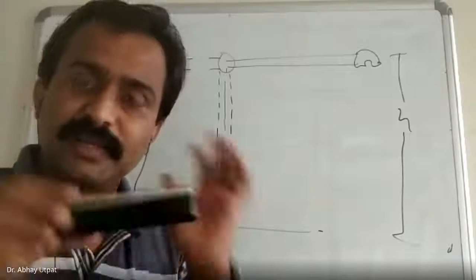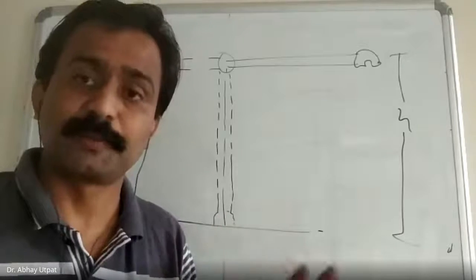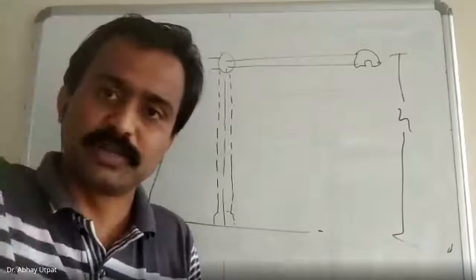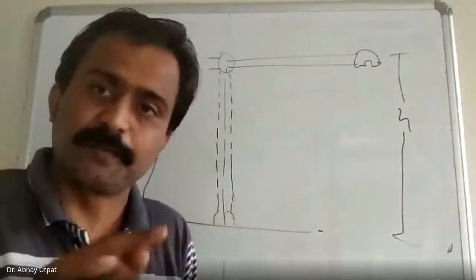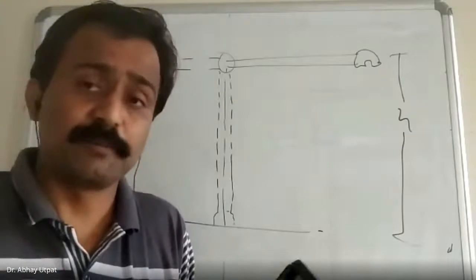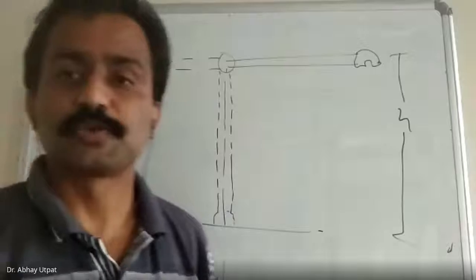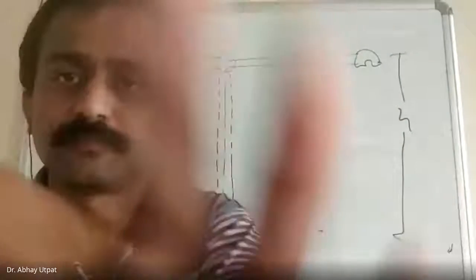That's why intentionally we are creating the notch. I hope you are getting the purpose of creating the notch. You are using a plain rod, but in actual condition, when it is acting as a shaft, it may have some stamp mark, it may have some keyhole, and because of stress concentration it may fail earlier. Understood? So please remember, bottom line, I will tell, last 2 minutes are remaining.